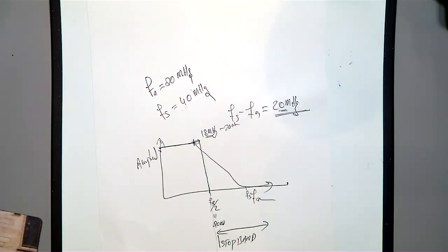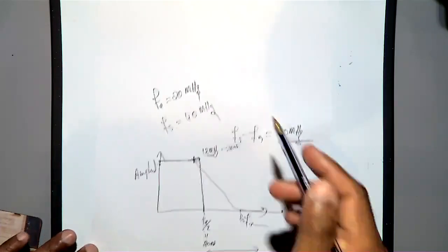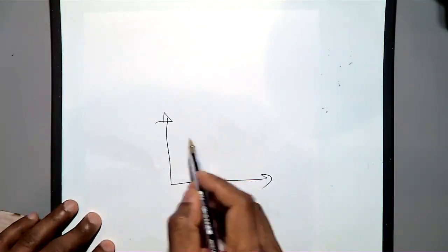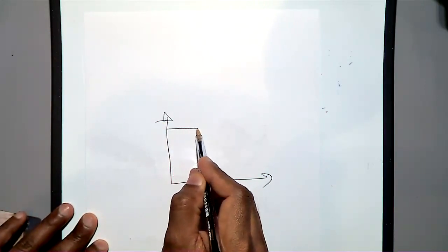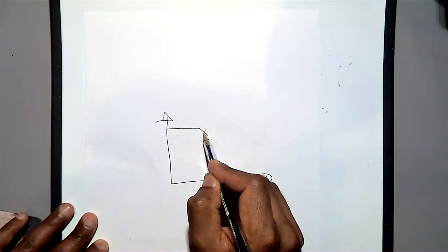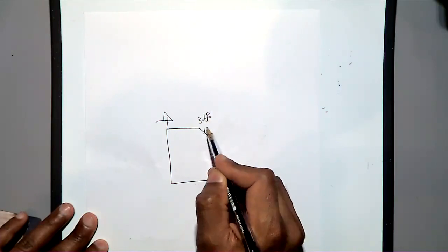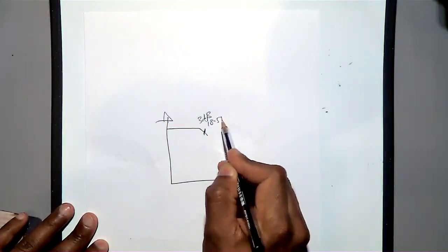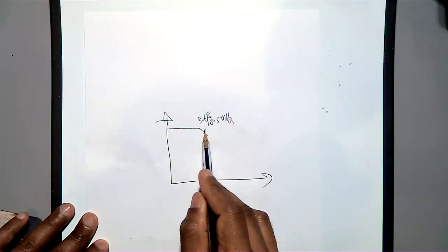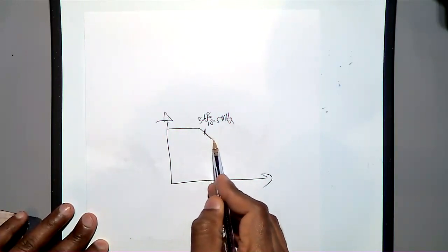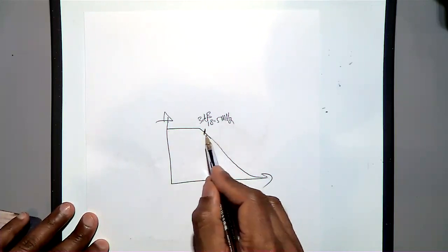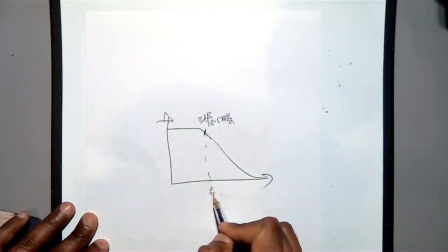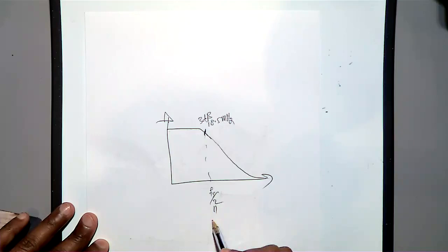So when you design it, you might be getting something like this. I'm not showing you because it got some marks. In your case, this is a 3 dB. So with 3 dB you can have maybe 18.5 megahertz. Depending upon your order, it will be coming like this. That is fine. And then this is 20 megahertz, and this is your sampling, Fs by 2. So Fs by 2 equal to Fb in your case.